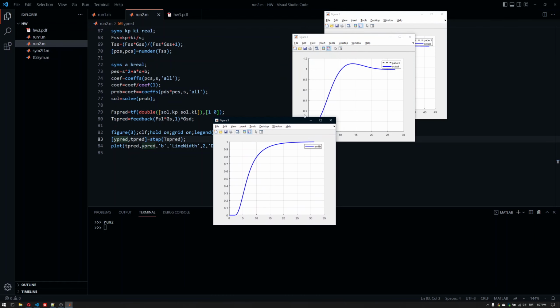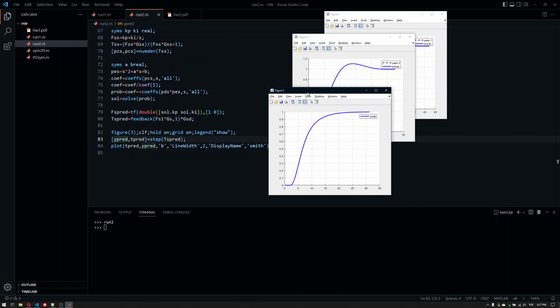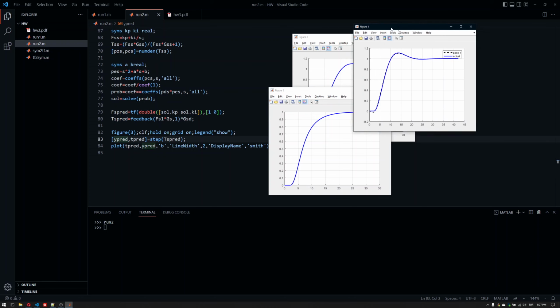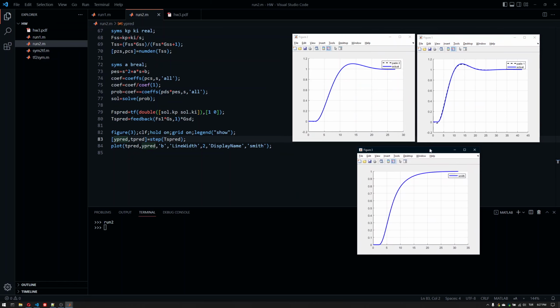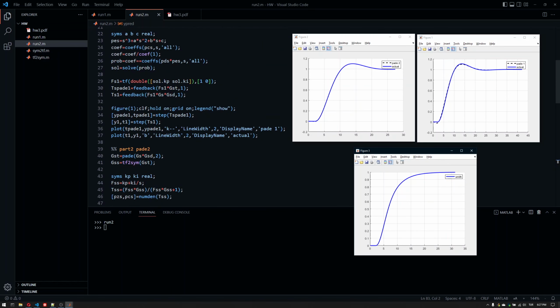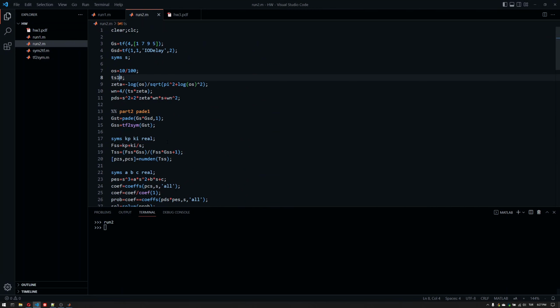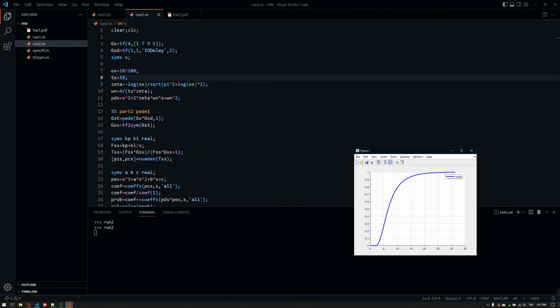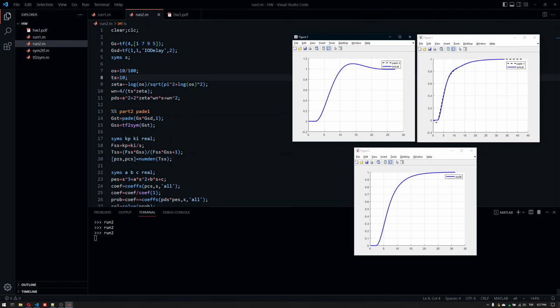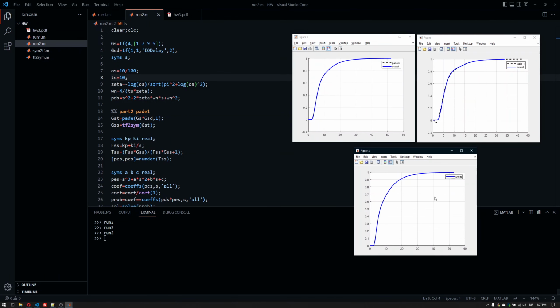So now again, the PI controller is not a suitable controller for this system. For this system specifically, if we choose settling time equals 10, then everything gets problematic. So let me just change that. Bode approximation is not possible to use, and it's also not possible to use for the Smith predictor.